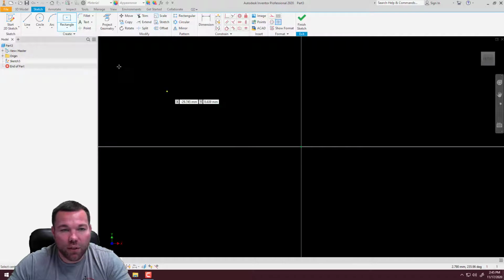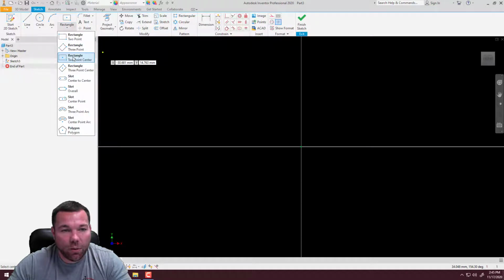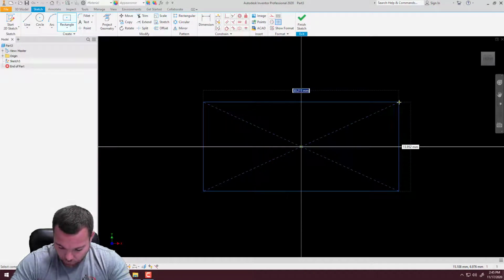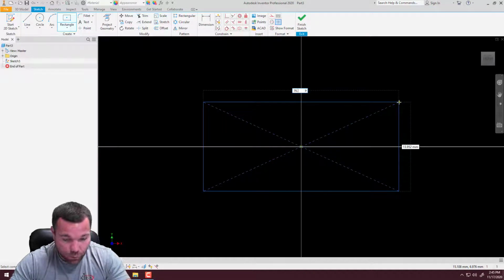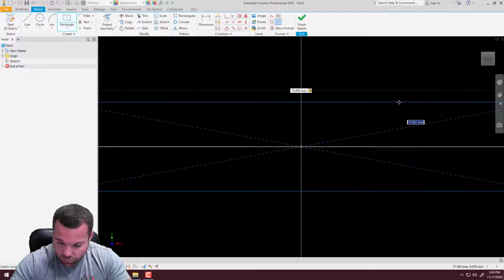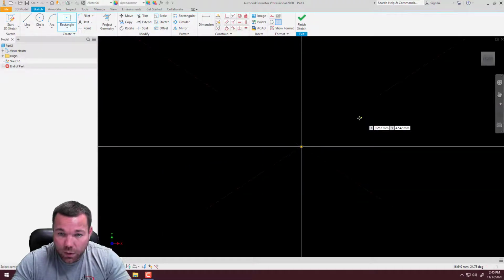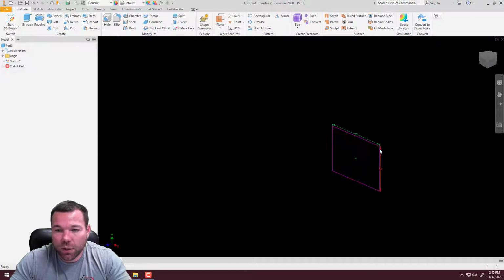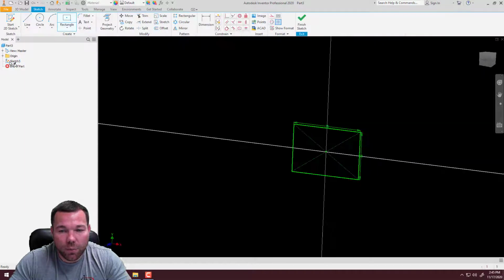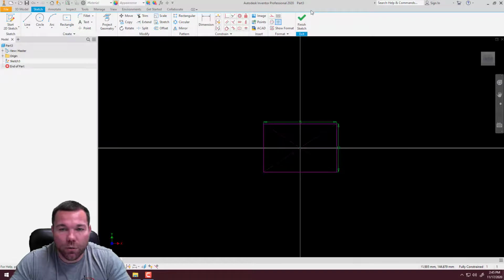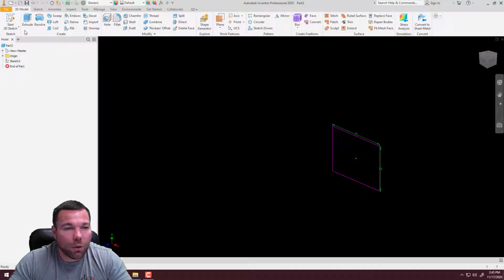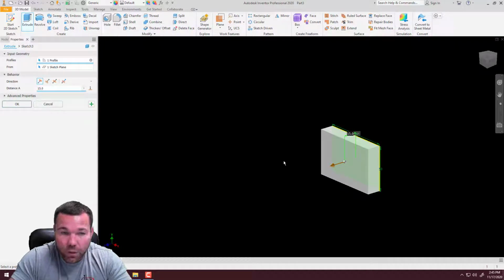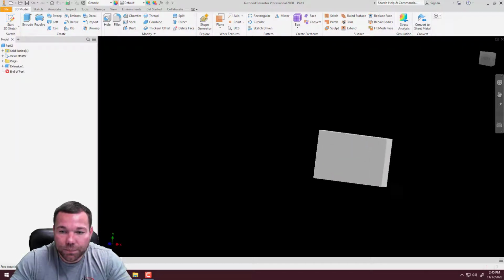All right, let's go ahead and create our sketch again. And I'm going to do a centered rectangle, so I can just go down and pick that rectangle to center. Looks like we're at 75 by 50. And there is our rectangle. Hit check. And I do believe, let me double click on that. It is fully constrained, so it's just double checking. I forgot to look. Extrude this, and we're going to extrude this 15.0 and hit check.